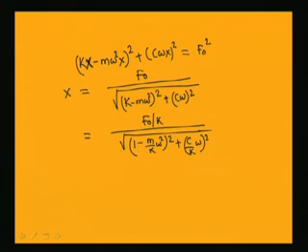Already you know that omega n square is equal to k by m, and also you know that c by m equals 2 zeta omega n. So, the c by k you can find.